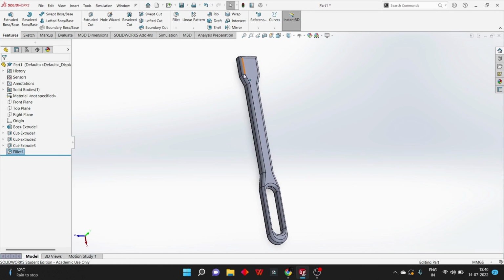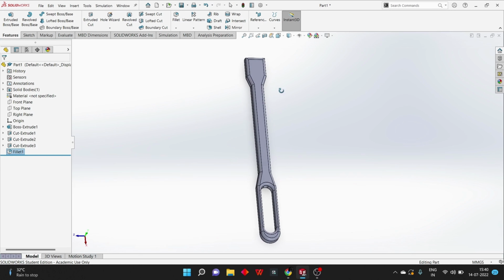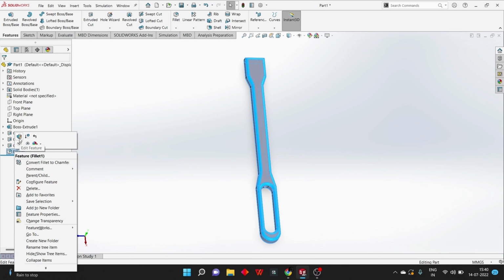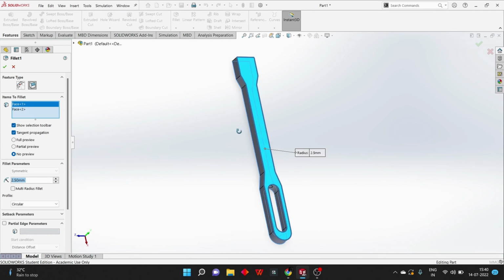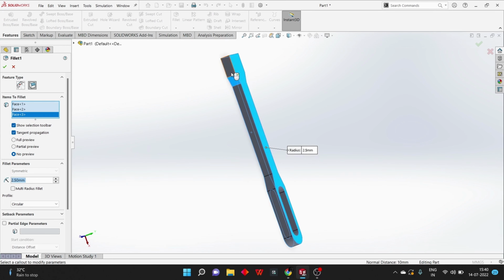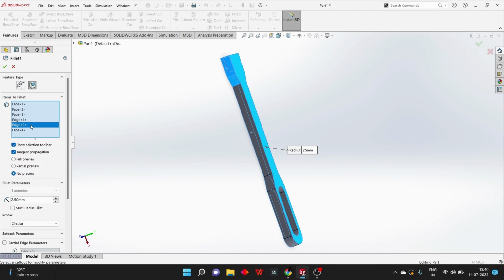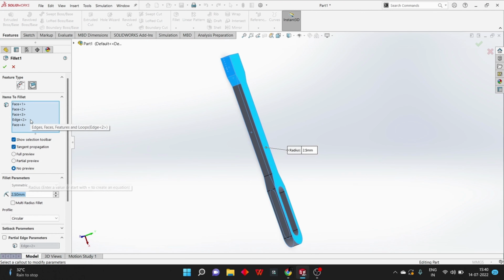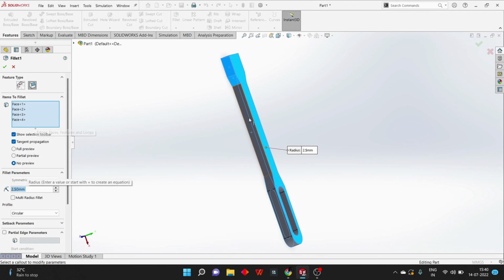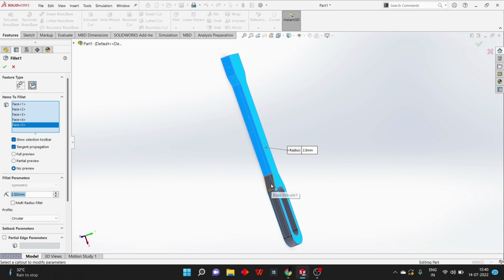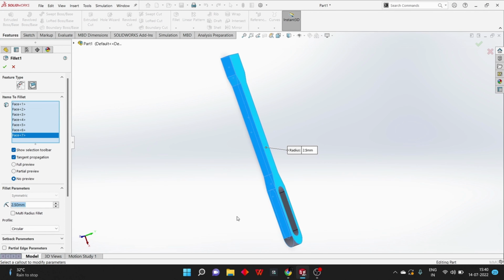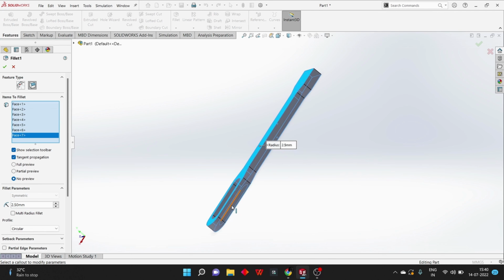Right. You can also smoothen the edges out. You can either go to the edit feature menu and select the faces if you like to. I'll just delete two edges. These are not the edges I would like. And select the faces. Similarly on the other side.